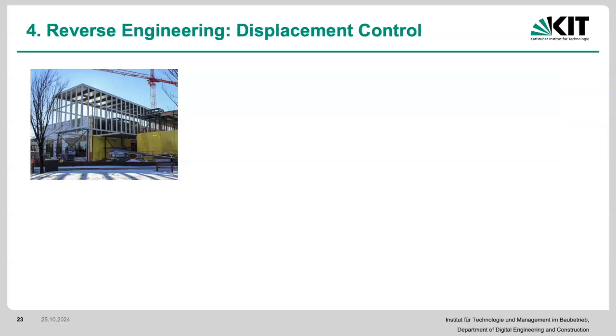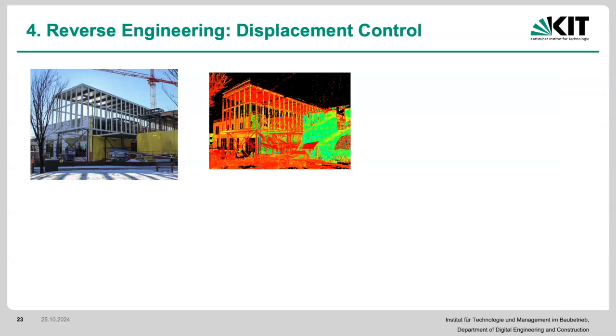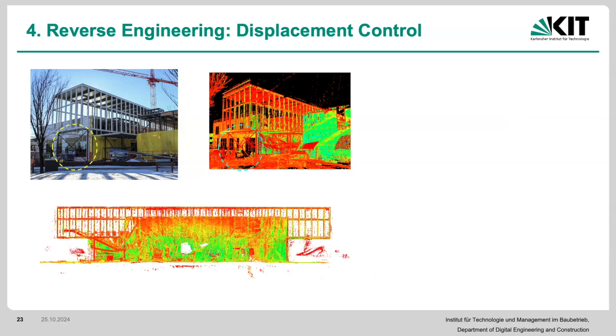Okay, so how can we use some of this information for reverse engineering? This was another construction site that I collected some data from. Essentially what this is, a cantilever beam truss. Cantilevers are basically, they have no supports on one side. And this was a long, I think, 20-something meter cantilever truss. And you can see here that there are some temporary bracings, right? Essentially, we wanted to see how much this displacement is once this temporary bracing is removed. So it looks like this.